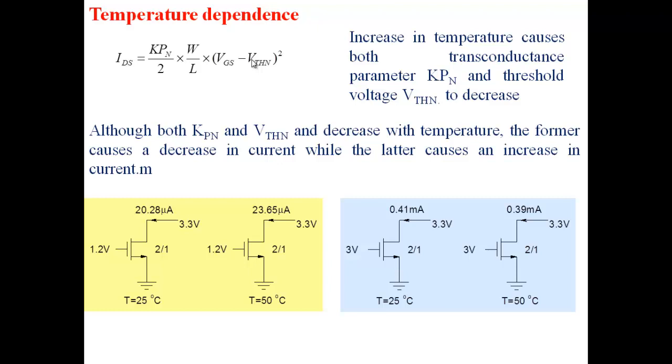So what I'm trying to say is that as you go towards higher voltages, when you apply higher voltages here, the current with temperature is likely to go down. Current will go down. So if you have a certain current at 25 degrees Celsius room temperature, and your IC turns the MOSFETs on, the current in a MOSFET would be lower at higher temperatures.